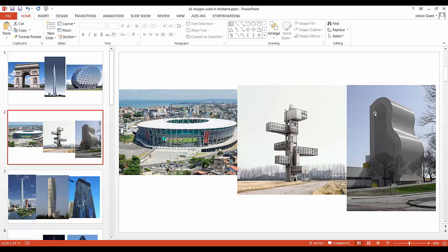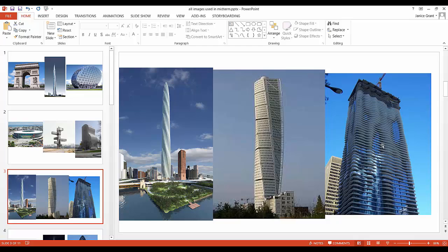Even in something as simple as this, you can create this shape on a reference plane and extrude it, or use create form to give it that depth. So most of these are pretty straightforward. In this one example, you can use regular floors and edit the profile of that floor, along with a tower of just regular curtain walls. So you might not have to use the massing for this one. It doesn't have to be this tall.